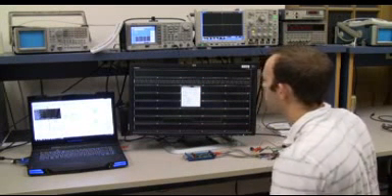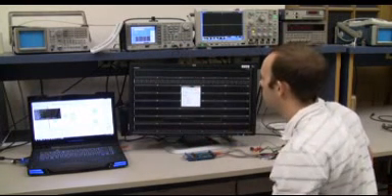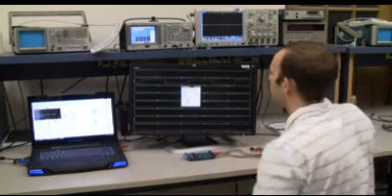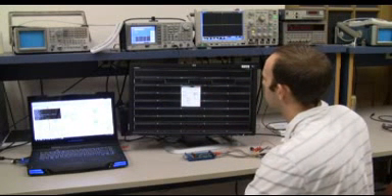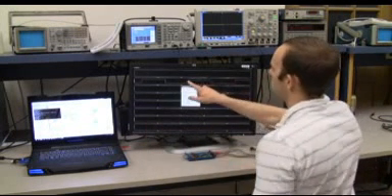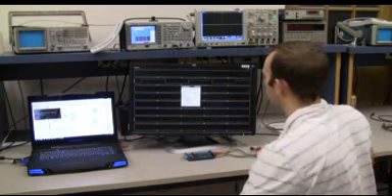We'll be taking 500 samples at 10 million samples per second. Click go. And here's our square waveform. To prove that we have multiple sampling rates, at 5 million samples per second, you'll get fewer samples of the same waveform, so they'll be compressed and there'll be more of them on the screen.